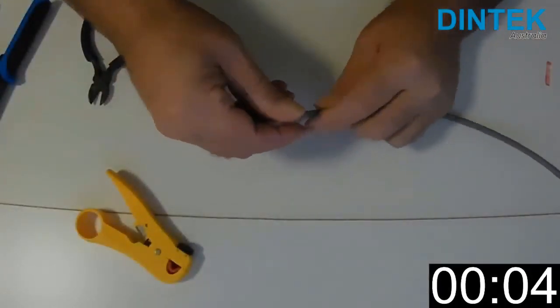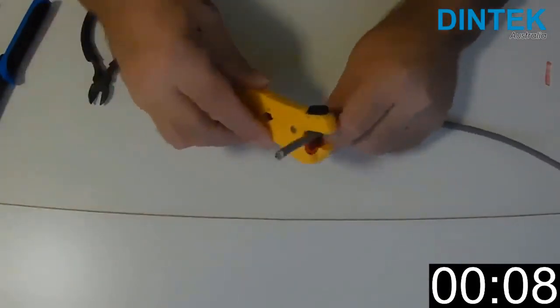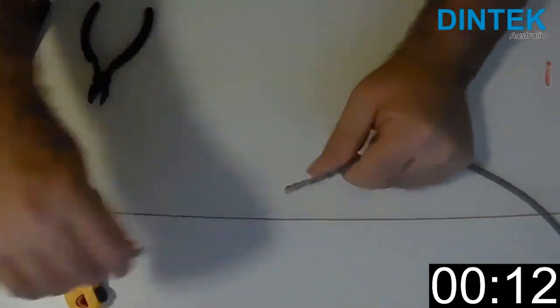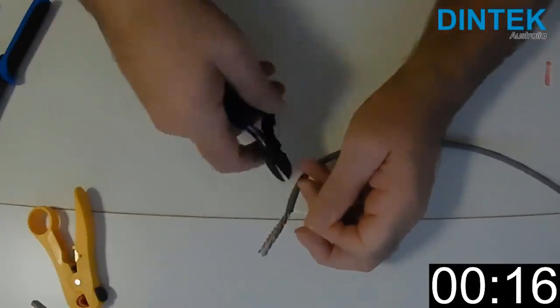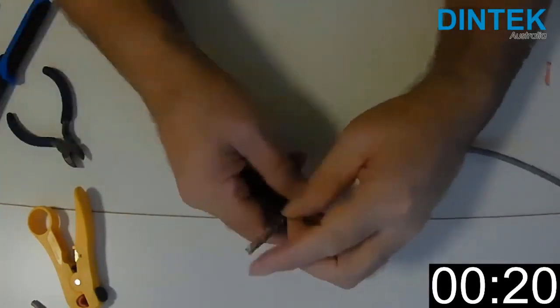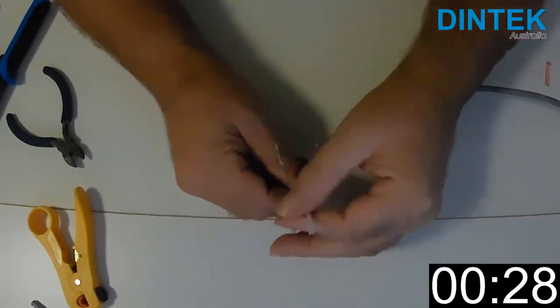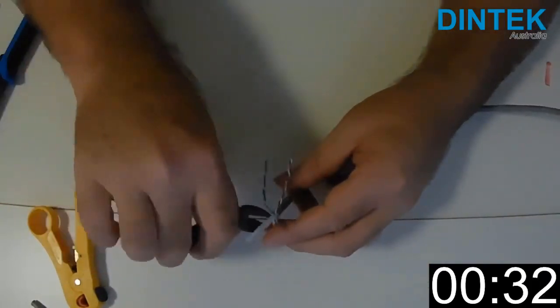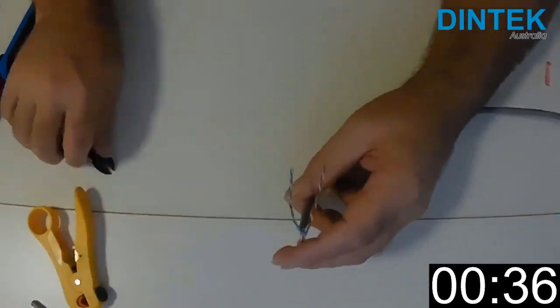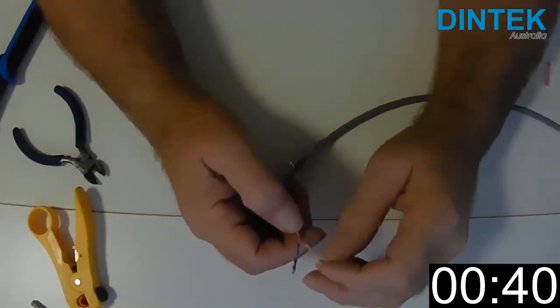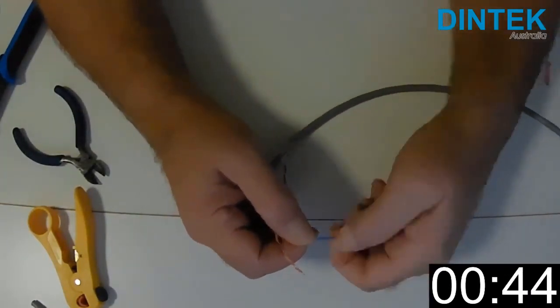Now we'll try a pass-through plug using the same Cat6 solid core cable. Exactly the same procedure so far, except I don't want to be as thrifty with how much sheath I strip off. The excess wires are going to be cut off anyway, and a bit of extra length will make them easy to get into the plug. Separate and untwist the pairs.